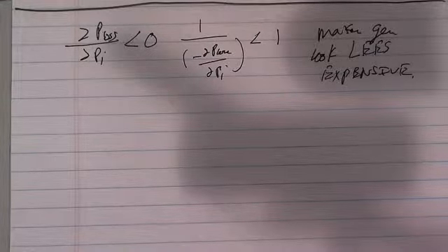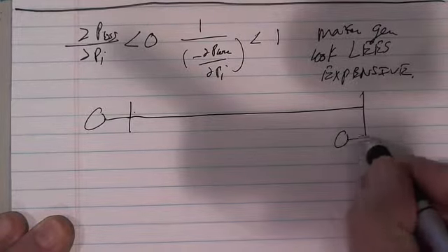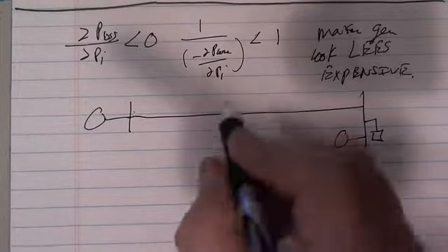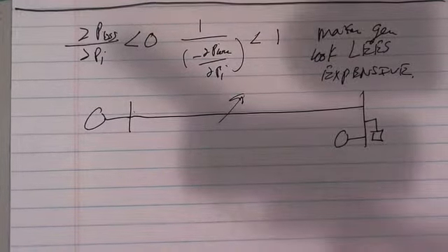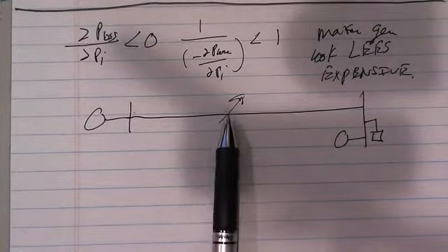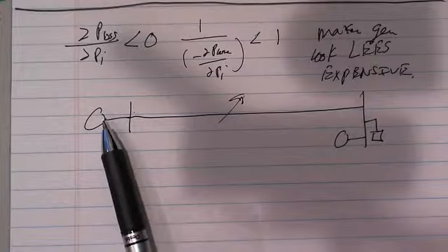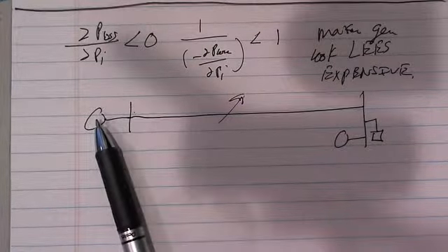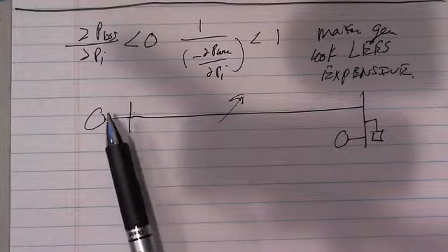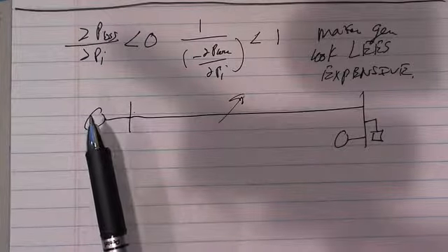There's an example in the book, and I took great pains to put that example together where you have a generator that sits out here on a long transmission line. You have another generator that sits up here and the load is located right here. And there's losses in this line. We said, well, let's just do economic dispatch, and then we'll supply the losses from this generator, so that if I want a certain amount of power here, then this one supplies that amount plus the losses.